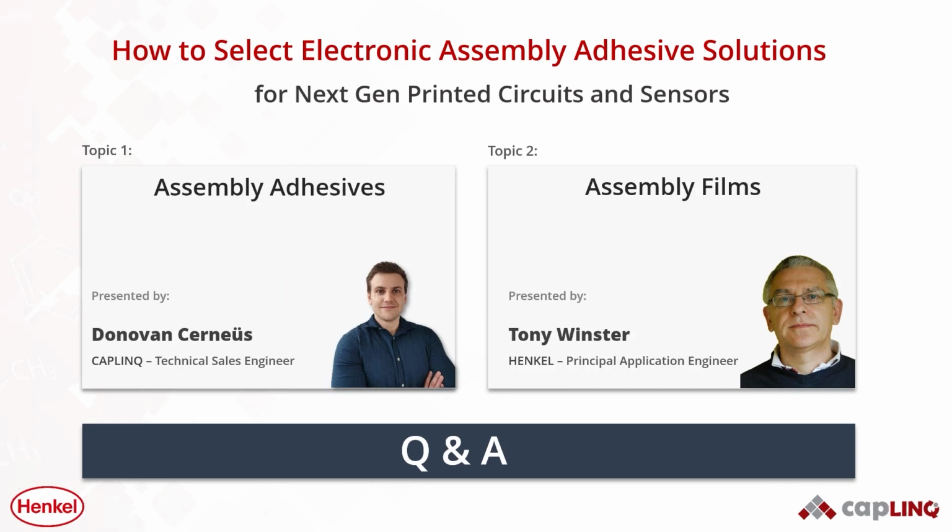The ACF, you mean a film? So what we've been talking about today is what we call assembly films, which are made as freestanding films. But there's also a separate product range that's designed for wafer application, where the film can be laminated onto the back of a wafer and diced, so the chip, or component, can be picked up together with its glue and put down on a lead frame. So I think that's the subject for a separate webinar.